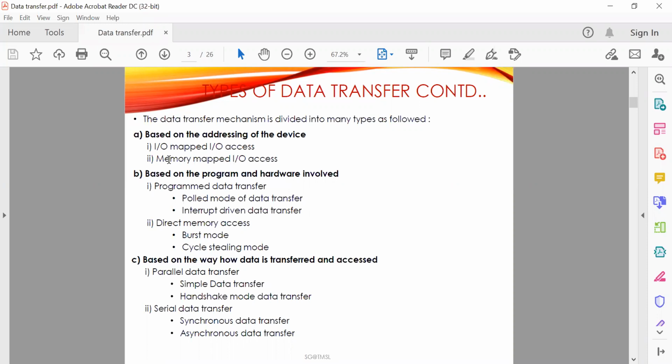Now in this type of technique, the modem plays an important role in serial transmission. What is a modem? It is a device that allows transmission of serial data over communication lines such as telephone lines. In general, communication lines are not capable of carrying the voltage changes required for a direct digital connection. Now, a modem overcomes this limitation by modulating digital information into analog signals using one of the modulation techniques and demodulating it back into the digital information upon reception.